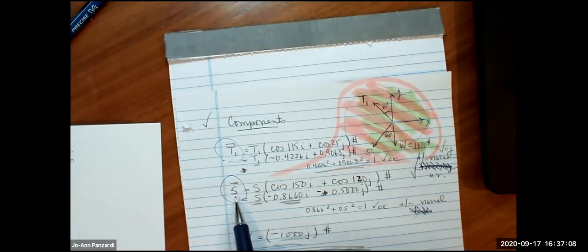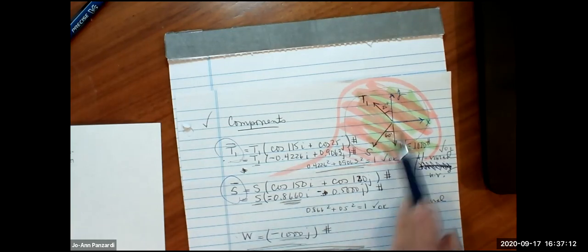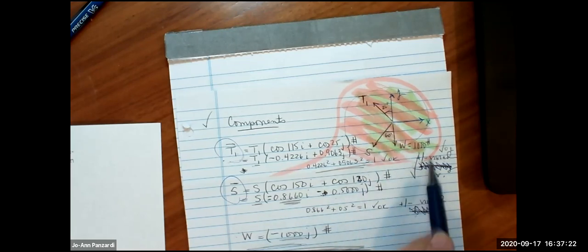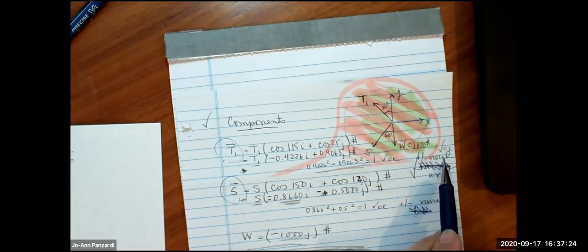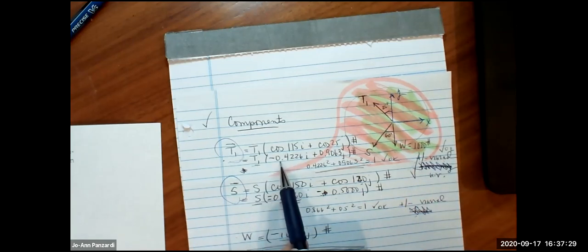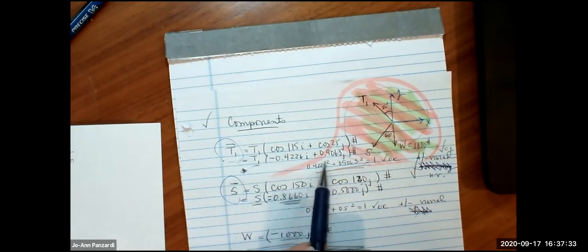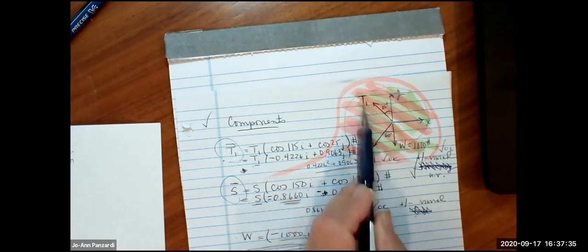Remember what I mean by the positive and negative. Let's look at S. S has a negative X. Look at the picture. Yes, X is going into the negative direction for X. S has a negative Y. I look at the picture, the free body diagram. Yes, S goes in the negative. Now I could do yes, plus or minus visual check. Same thing for the tension. I got a negative in the X. Yes, T1 is in the negative direction for the X. For the Y, it's in the positive.